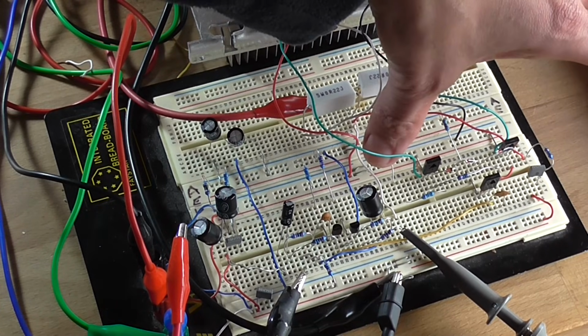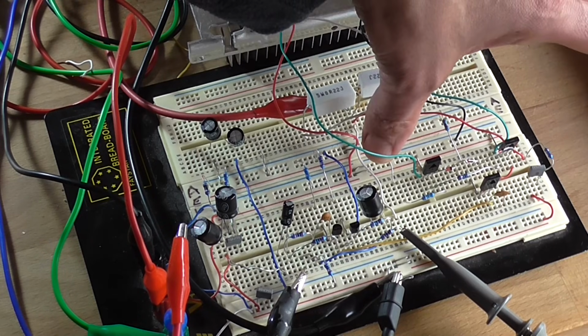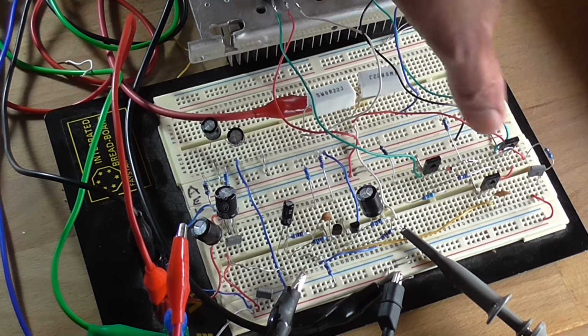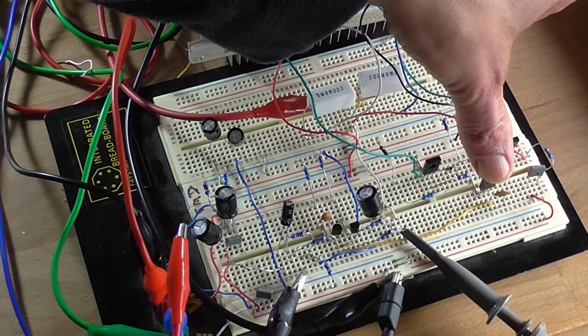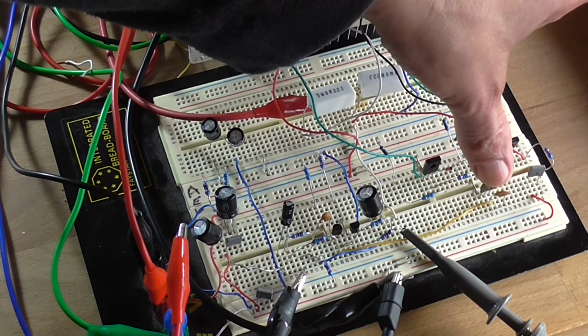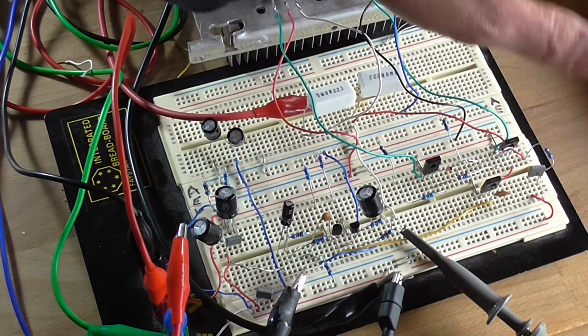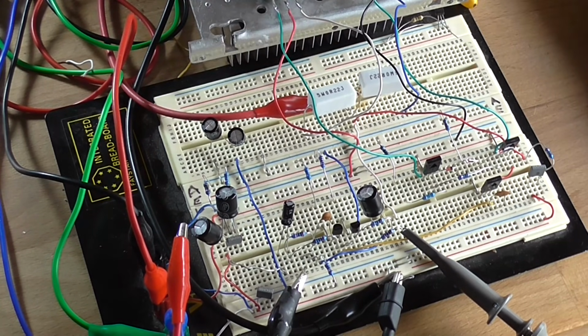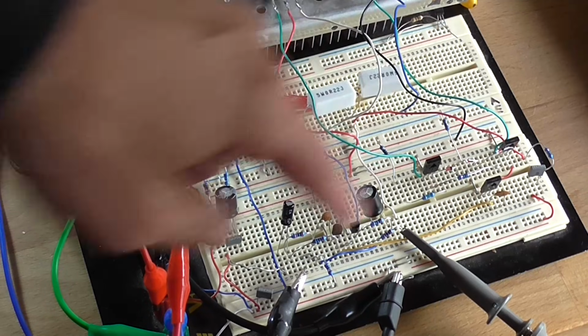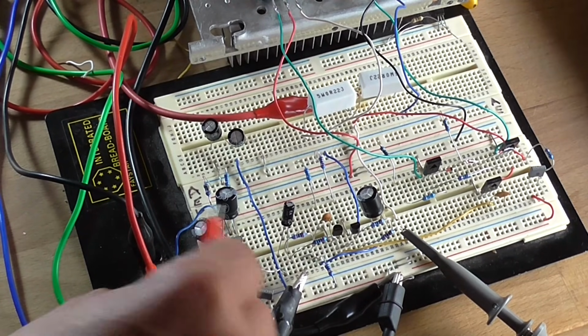However, these 680 ohm resistors are getting quite warm, as I said they would, and so is the VAS, but there's like 20 mA going through that, or close to it. So that's about a watt of dissipation. So it would need a heatsink on the VAS and most likely 1 watt resistors here for the 680s, if this was to be the final design, which it is not.